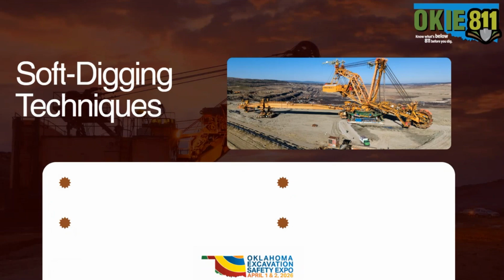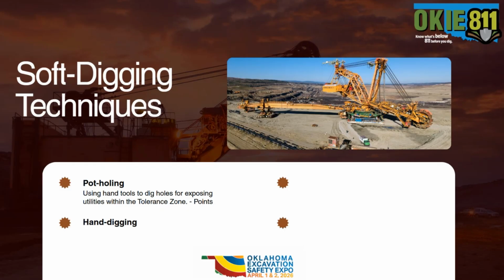There are a variety of soft digging techniques, and here are some examples of what that would look like. So, potholing. This is using hand tools to dig holes for exposing utilities within the tolerance zone. They are points at which you are digging a hole to confirm that location if you're working around it.